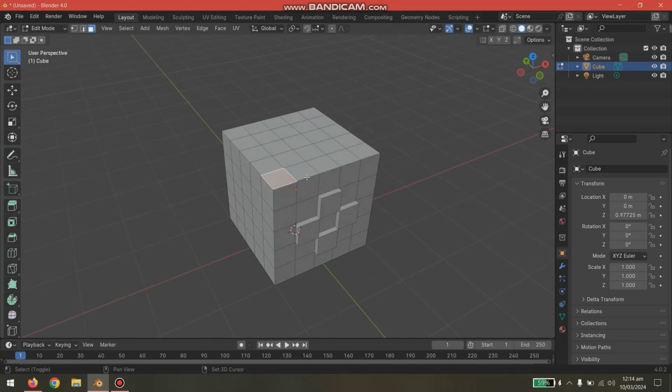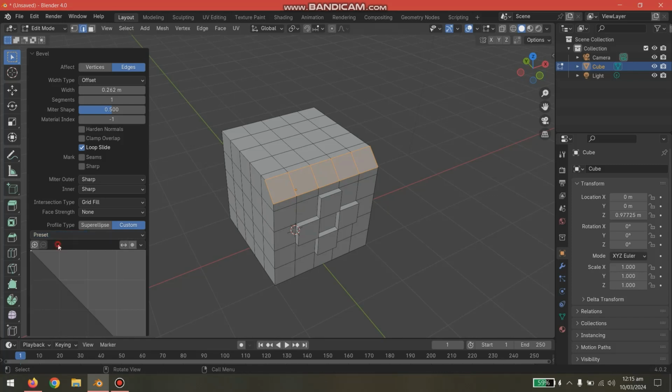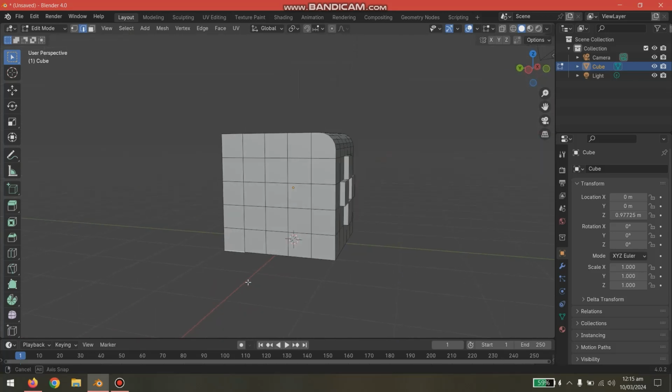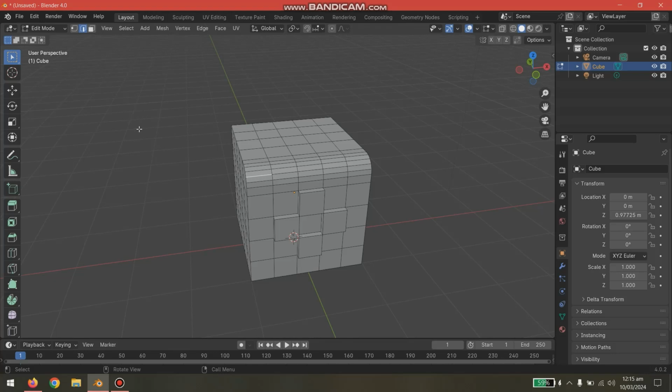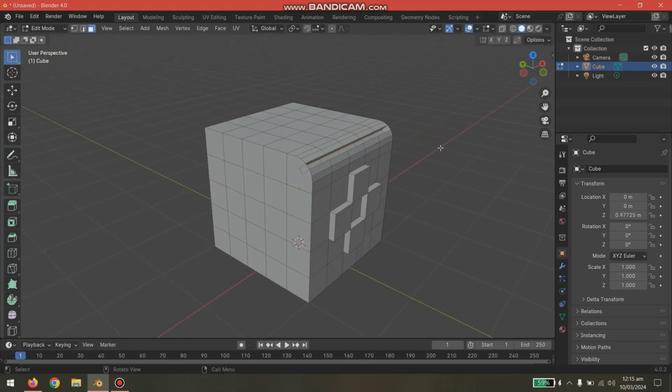And the same thing we will do with the bevel. Now you can see here I'm combining subdivide, bevel and extrude, and press Ctrl B. You can also do this. Okay, this is how it works. So I'm gonna do default super ellipse because we want curves, not stairs here. So this is how you did the curve section here. Now when you create a bevel, it actually subdivides into different segments, and this is how it will look. Okay, you can see here now it's bevel.